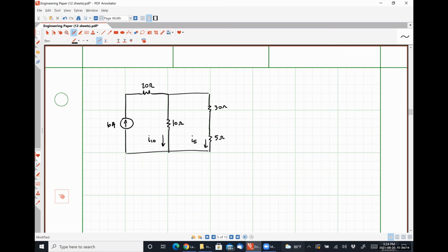Okay, that's the key. So you're correct that it is going to introduce a voltage drop into the system. That being said, current division is allowing us to calculate currents without ever knowing what any voltage in the system is at all. So that doesn't particularly matter, right?